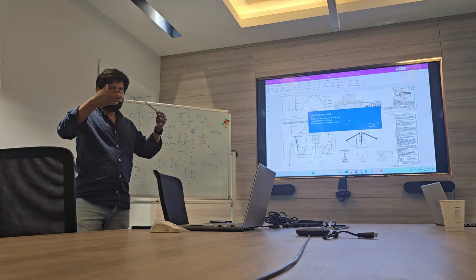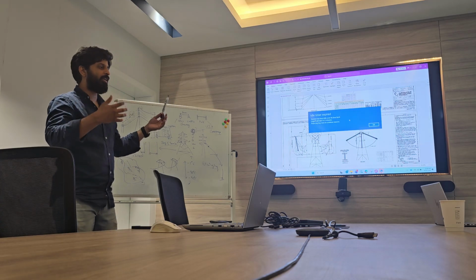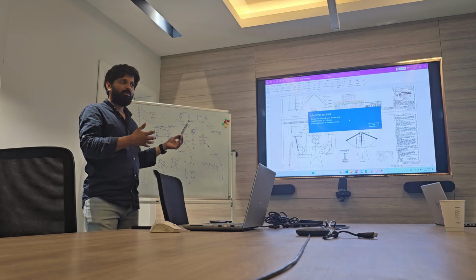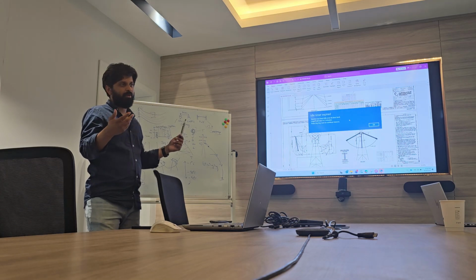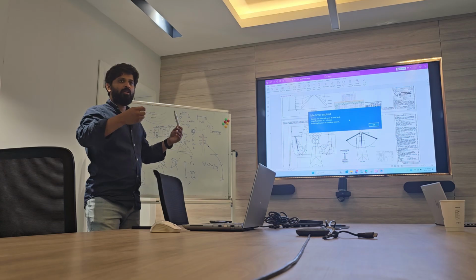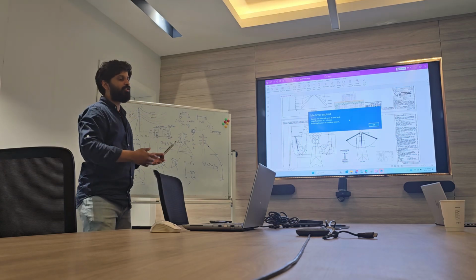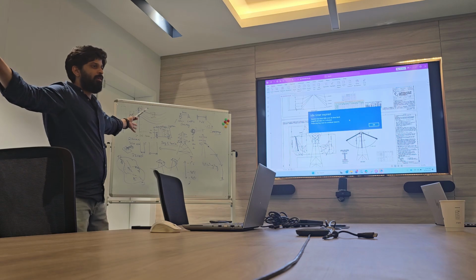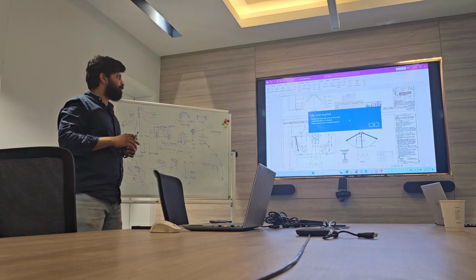I allow that conductor to relax. When I make the sag almost zero, it is dangerous for the tower and dangerous for the conductors. You will pull it, it may break. You have to apply too much tension, it may break. Apply too much tension, it does not have room to move. If you make it too loose, it will move too much. You need a bigger right of way, it has more clashes, you need a bigger cross arm for it to not touch the structure. Many things like this.